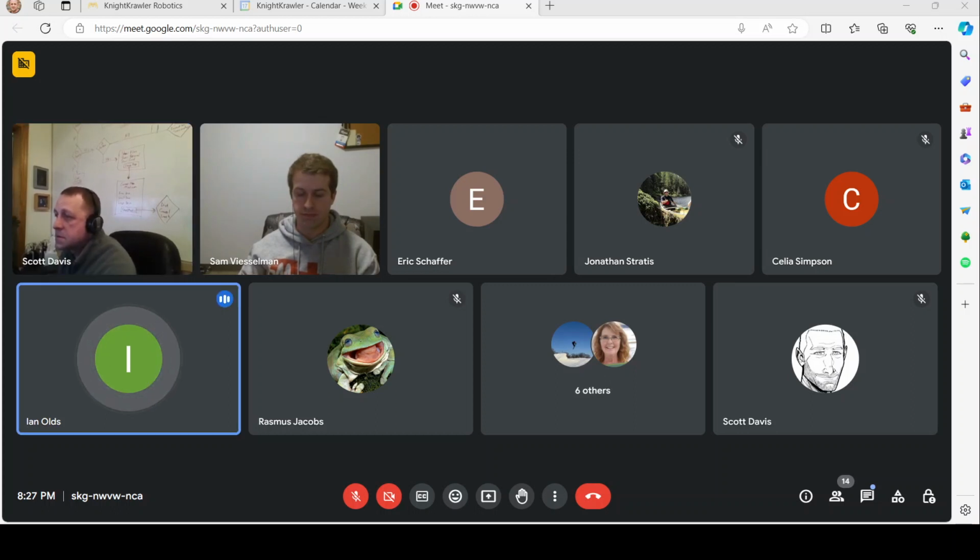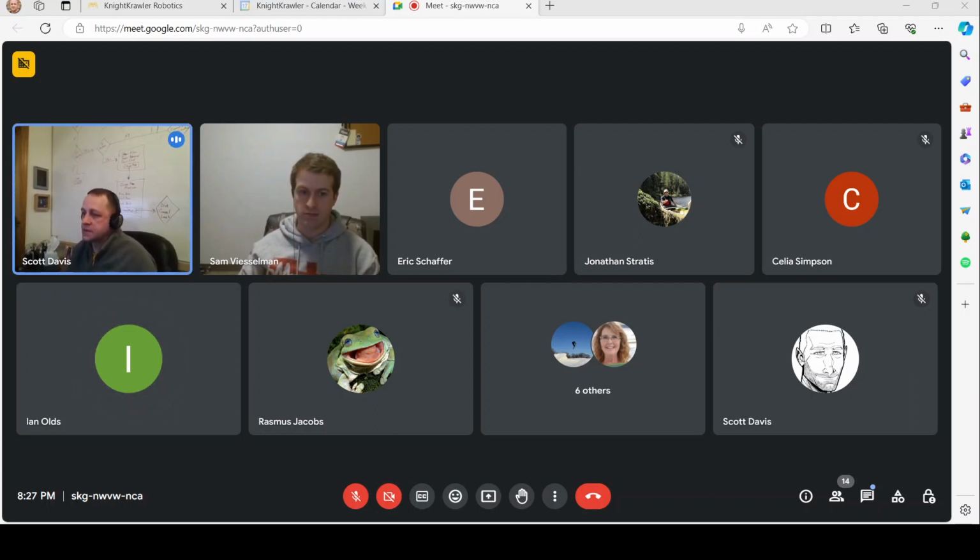We just don't allow it to reset our actual position; our odometry class just doesn't. It'll only update the X and Y coordinates from that. Oh, I see. So we get the X, Y, and theta in from the April tag, and we only use the X and Y. Now I understand. Okay, that makes sense. I've only looked at that pose estimator code once or twice, so I will be passing this information on to Caleb. Thank you.